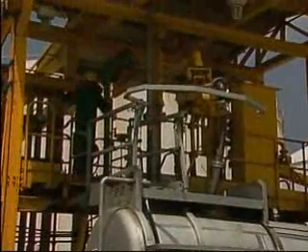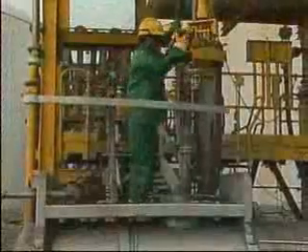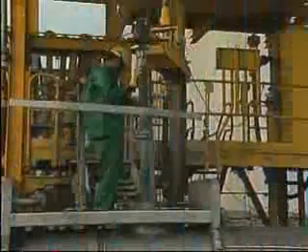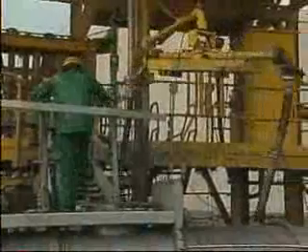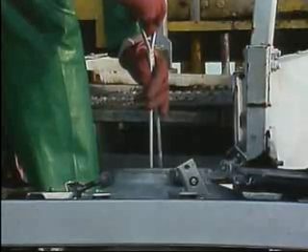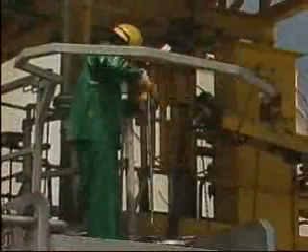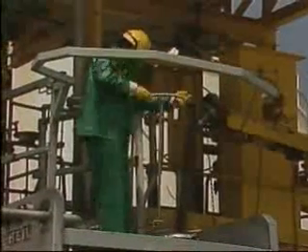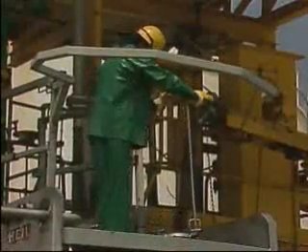The first thing that the operator does is shut off the pump. He then closes the loading valves in the reverse order from which they were opened. After closing the valve on the loading arm, the operator removes the loading line from the manway. He also takes a sample of the liquid for analysis to verify that the product meets specifications. Then he bolts the manway cover back into place using a crosswise pattern to evenly compress the cover gasket.